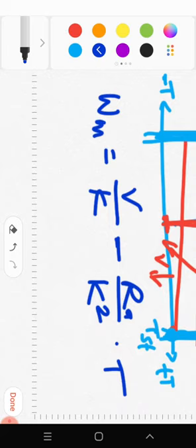It can be increased. It can be increased by adding external resistance into the armature circuit. So now the resistance term, the term in the numerator, is now higher. So due to that, slope will be again higher.